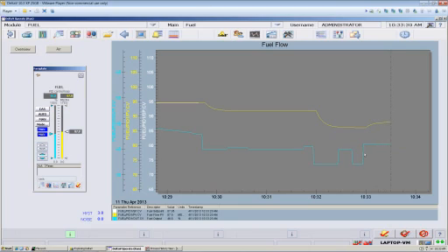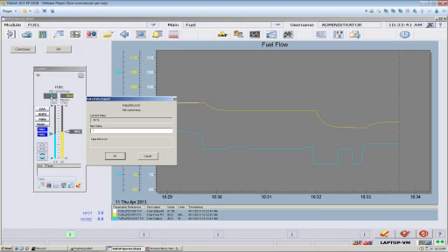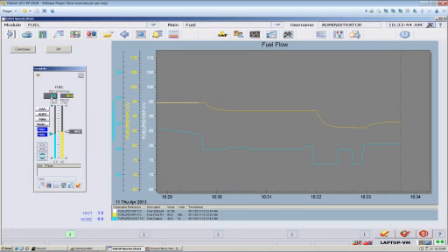So now that I found out I've got this hysteresis or this sloppiness of 3%, now that I've made a change big enough to actually affect the flow rate, let's make another step in the same direction. And now I learn my true process gain. My 2% output change here is going to result, and I know it will result because it's my simulation, in a 2% flow change. My gain is 1.